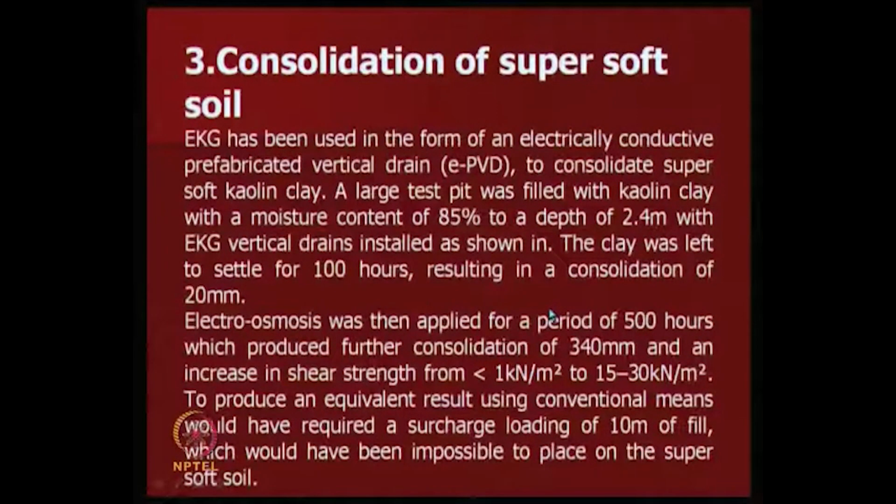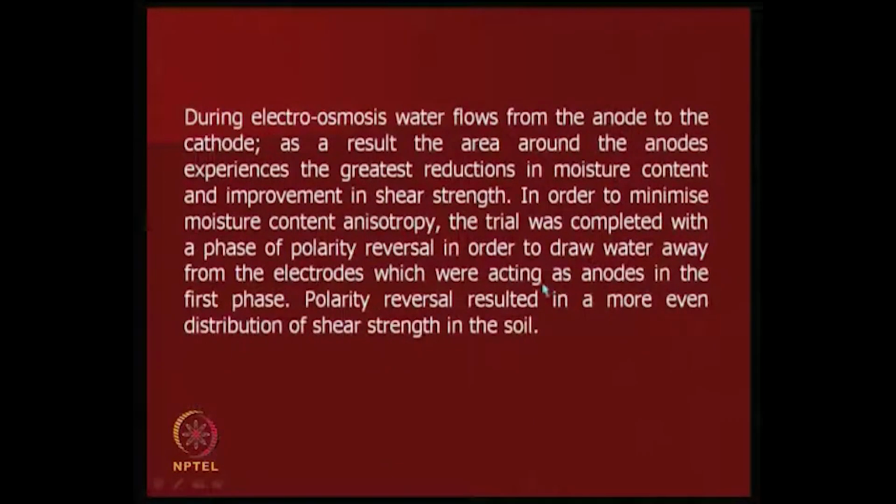We also talked about PVDs just now, about 2 classes before. Here also you can accelerate the consolidation of PVDs using this, and there was an experiment done, and electro-osmosis was then applied for 500 hours, which produced further consolidation of 340 and an increase in shear strength from less than 15 to 30. It is quite excellent.